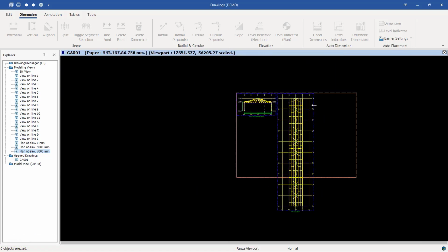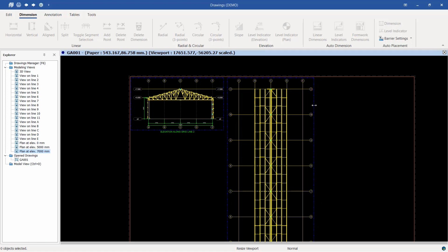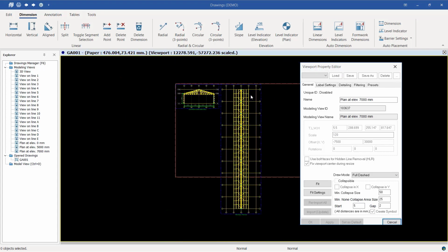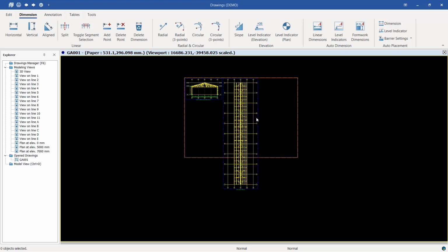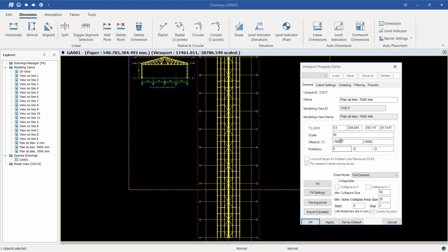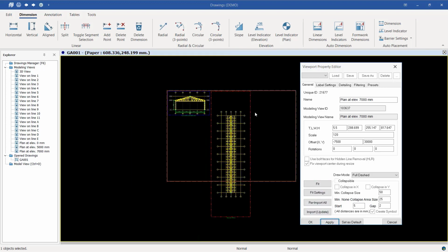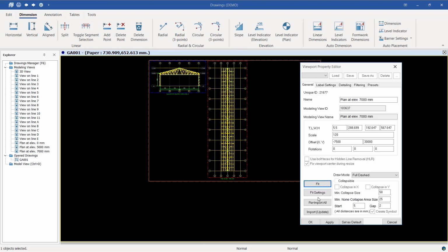It's so big that it extends beyond our defined boundary where we intend to place our drawing. So I'll double click on the viewport here and change the scale to 120 and apply that and give it an OK. I'll cancel that, double click on it once again and change the scale to 120 and apply. So once I've applied that, I'll come here and fit. You can see the viewport is way big, so we can fit it so it fits well in here.